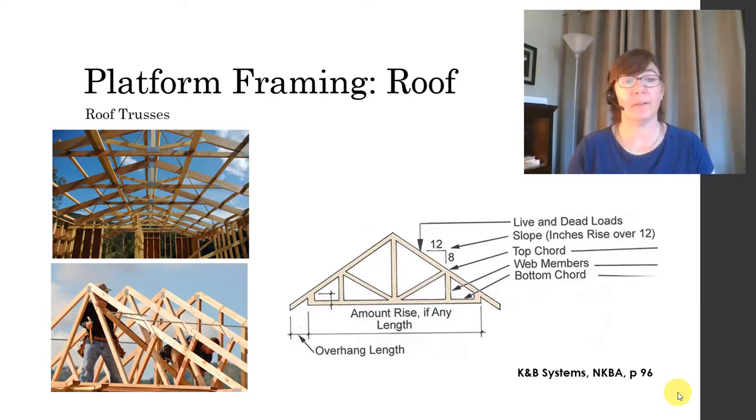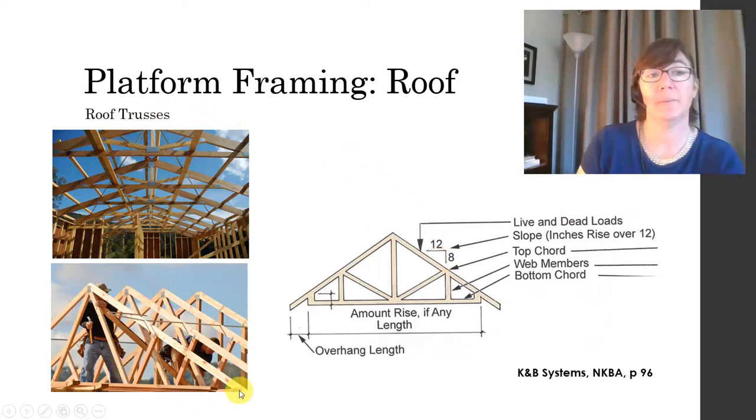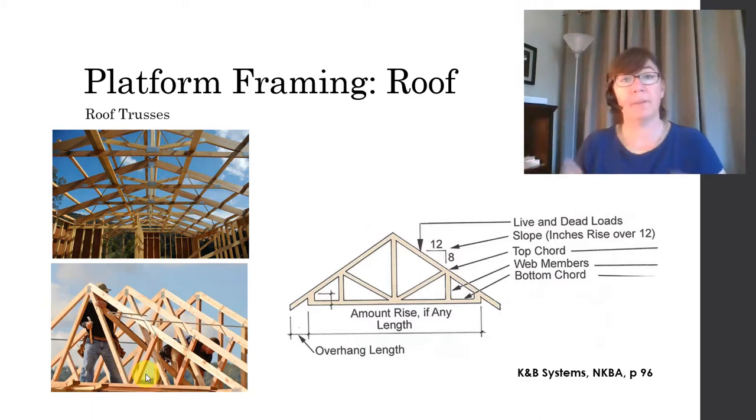All right, so here's what trusses look like. It's a couple of vocabulary words. Here we go. This is a truss. It has a bottom chord. Here is the top chord, right here, top chord. And any of these pieces in the middle are called a web, kind of like a spider web. All right. So bottom chord, top chord, and web. And finally, just like the rafter, your truss will have a slope. Okay, rise over run. Here's what trusses will look like out in the fields. And they come prefabricated, they are shipped to the site, and then erected onto your structure there.